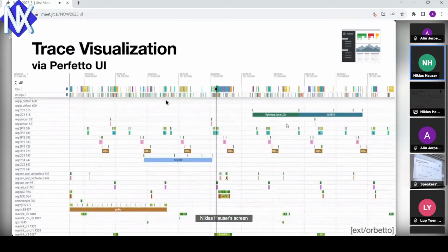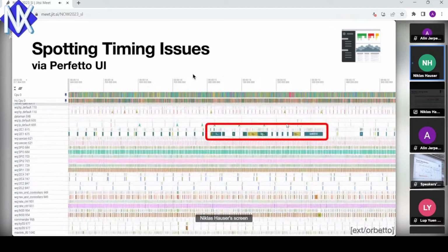And yeah, if you zoom out a little bit, you can also see patterns appear because, of course, we're polling the sensors every couple of milliseconds. Here, each tick is 1 millisecond, so it's 10 times more data zoomed out. You can see the SPI buses getting read periodically. And then if you zoom out even further, every tick now is 100 milliseconds, you can see a hiccup.